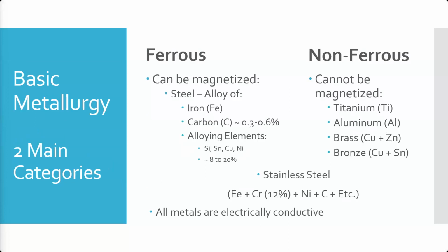The next thing we're going to look at is the materials that parts are made out of. Materials can affect what kind of tests you can perform. Materials can affect how those tests act when they're performed on them. An ultrasonic test performed on metal is going to behave differently than an ultrasonic test performed on a composite.